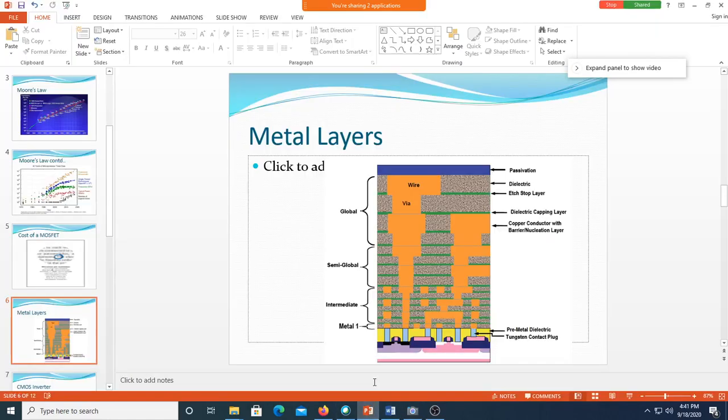In such a case, since the number of transistors is huge, the number of metal layers required for interconnection will at this point be 12 layers. So you need 12 different layers of metal to have the connection among the circuits at the bottommost, where you have millions or billions of transistors. They have to be interconnected properly as per your requirement. If you want to make the connection, you need metal lines, and that n is almost 12. So you're going to have 12 different layers.